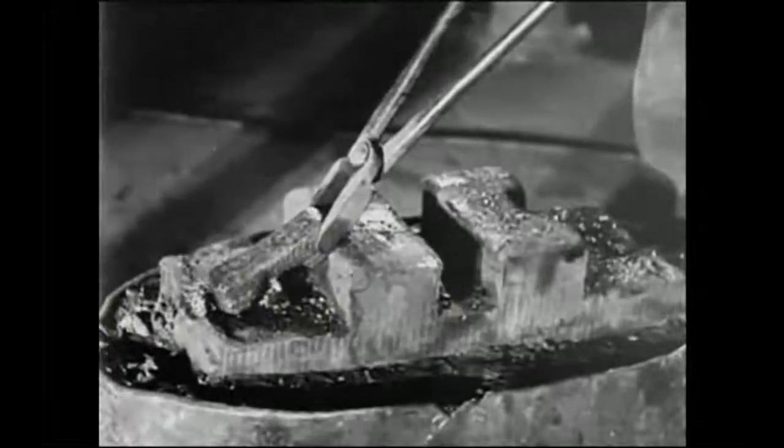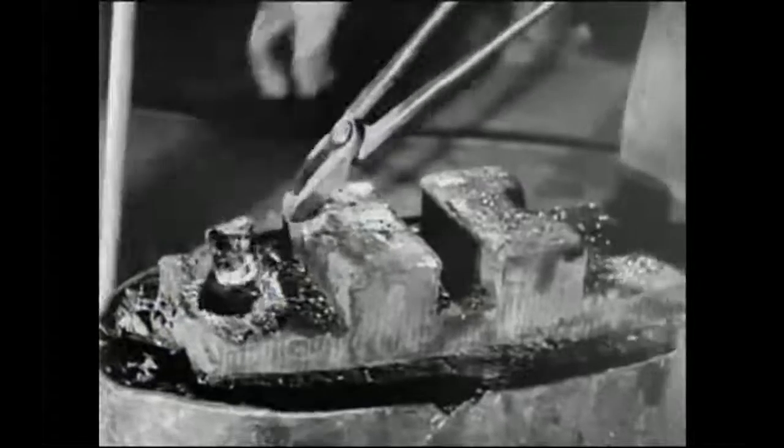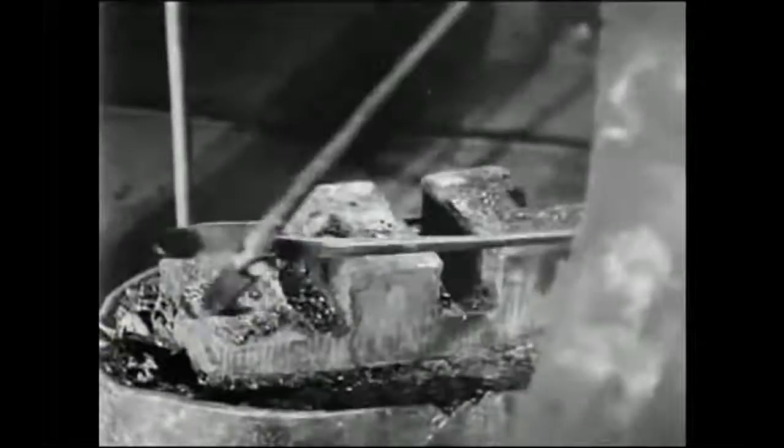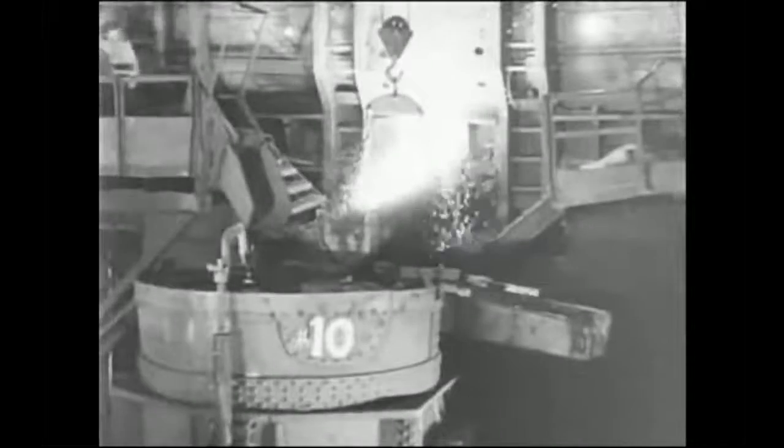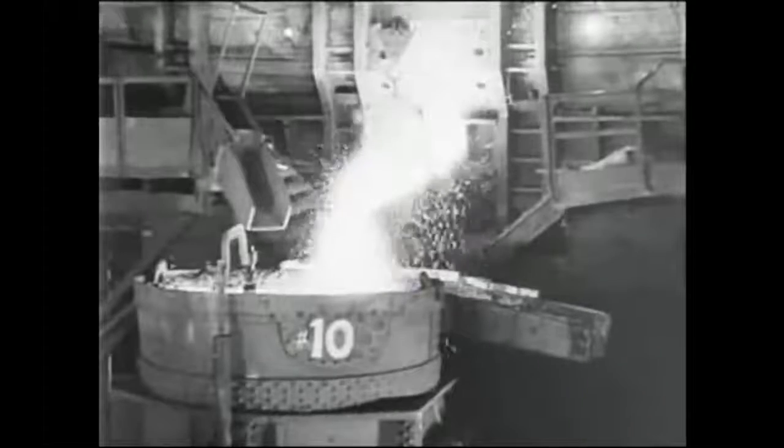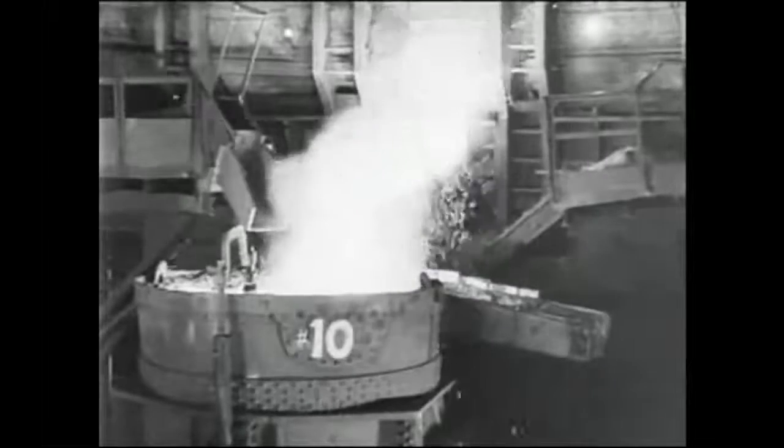By inspecting samples of the molten steel, the boys could tell exactly when the furnace should be tapped. The open hearth gang ravels out the hole in the rear of the furnace and lets the steel out, roaring and spitting at 3,000 degrees. The pit gang dumps in alloys to give it the special qualities they want in this batch.